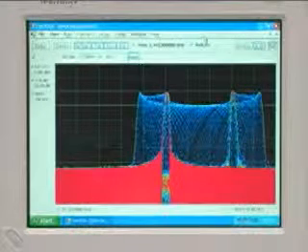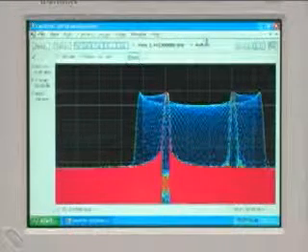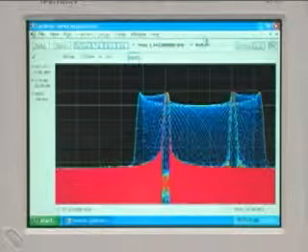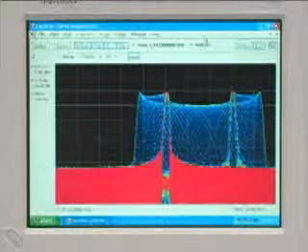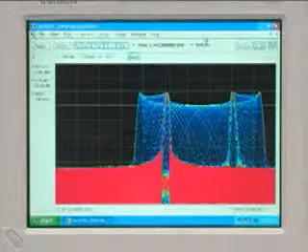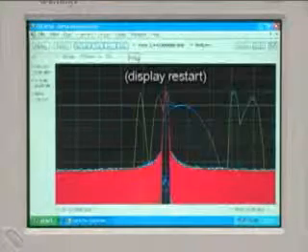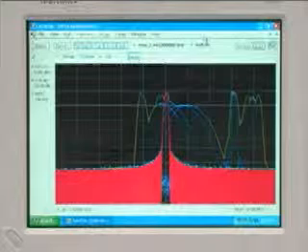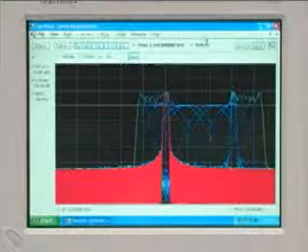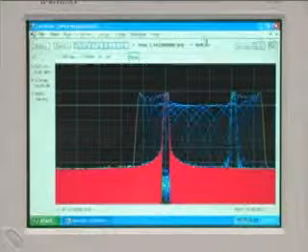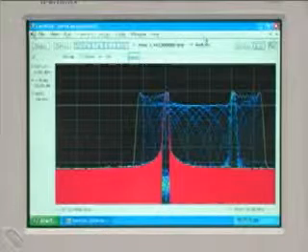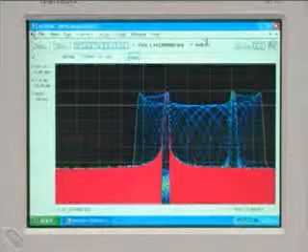Because we're referring to temperature processing, events that happen more frequently get a higher intensity or hotter color assigned to them. This way we get a much better sense of the time-varying behavior of signals. By capturing and displaying the signal like this, we can very quickly see a similar envelope for this particular signal, which took several minutes to show with the Agilent PSA.